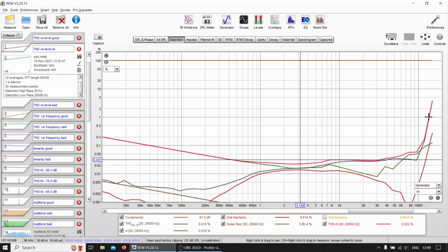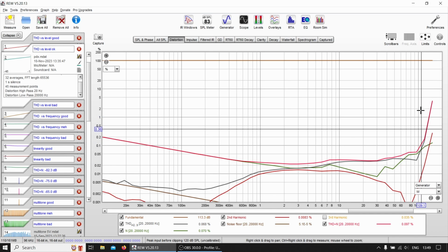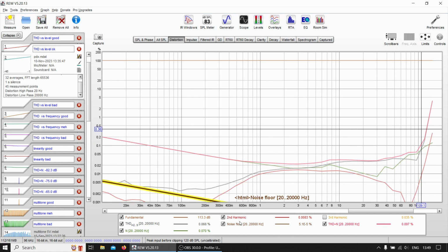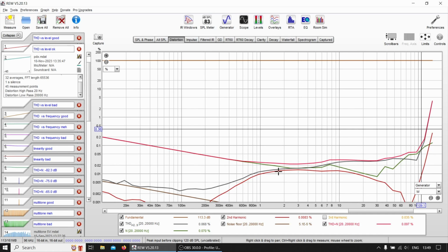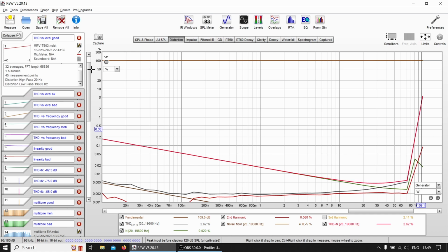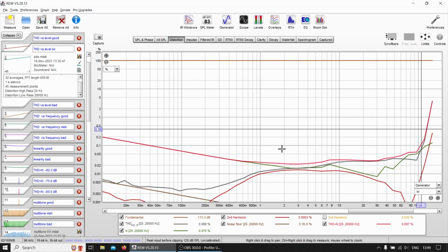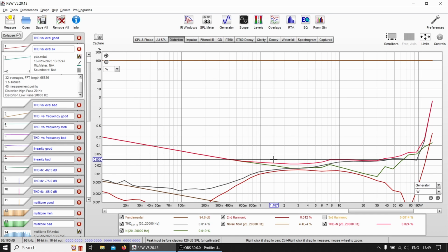However, on this one, we can see that it has a bit more power, at 1% THD it's like 130 watts, but again, those watts don't matter. And here you can see there's a different composition of the THD. The second harmonic, you can see that it goes like this. We will be talking about harmonics a bit later when I show you the 1 kilohertz sine tone. And I probably didn't mention, this THD versus level I measured with a 1 kilohertz sine tone. It's, I want to say, an industry standard. So this amplifier performs a bit worse, but it's still very, very good performance.